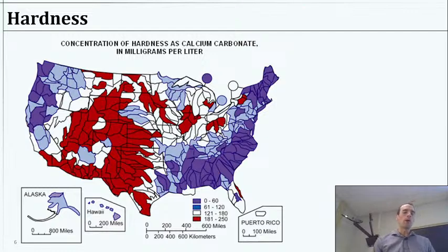So there could be some problems where the aesthetics themselves get to be too big of an issue. And this is actually part of, I don't think we have such a good quality map for Nicaragua, but that might be kind of neat if we could. But some types of ion removal, there are a couple spots in Nicaragua where that would actually be really helpful. I briefly looked into it last year, some ion exchange type stuff. So we'll talk about it, and that's one of the research topics. If you have too much stuff, it's kind of healthy otherwise, but it just is a bit salty. It's a bit too much minerals, maybe too much sulfur, sulfate. Could be a clean but too much minerals, and an ion exchange system or some other way to remove ions might be a good option.